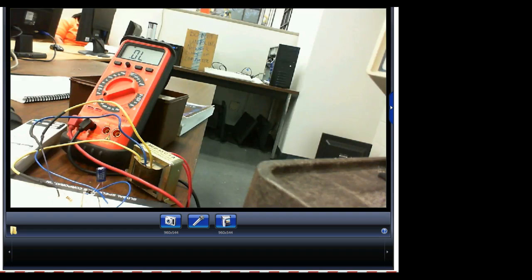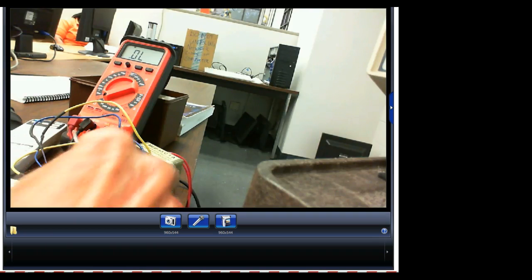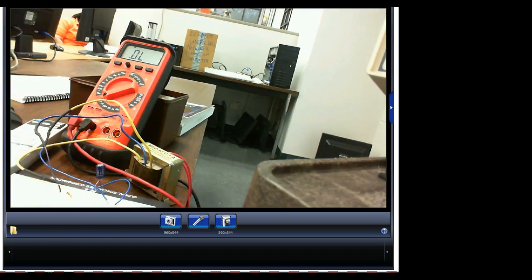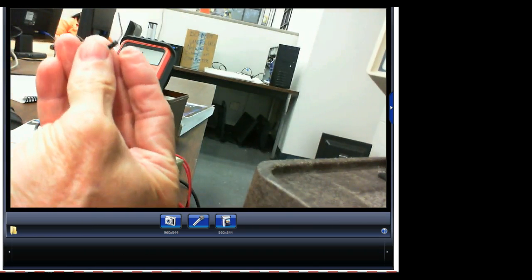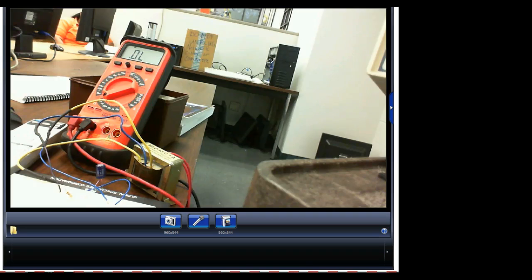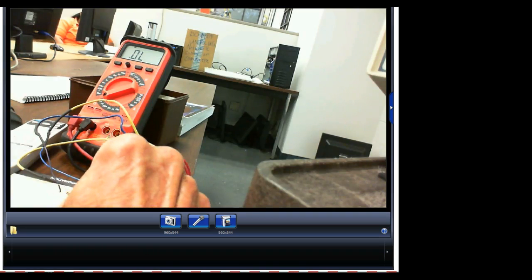And then I come over here, it's measuring way high. I come up here and get this guy, and I forward bias it, and it's measuring about 0.6 of a volt, which is usually what they measure. And then I'll swap it around here. So this diode right here is good. So there's a problem with this diode right here. When I had my scope going a while ago, I noticed something different, but I didn't take them out and check them.